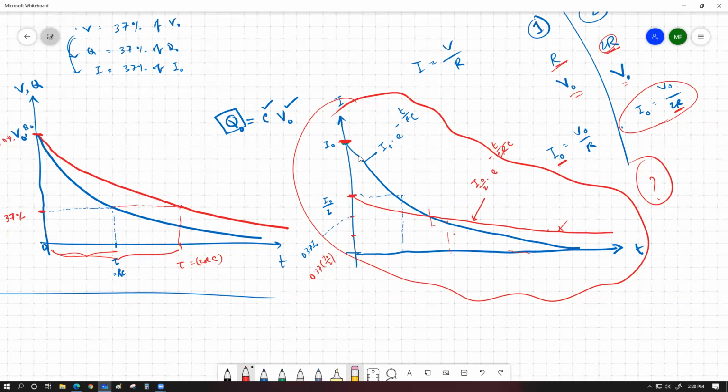জি স্যার। The next thing is how we are going to discharge. This graph is going to discharge with this ratio, e to the power minus t by RC, whereas this one is going to discharge by e to the power minus t by 2RC. So this one's discharging rate is significantly less because the power is half of what we have over here.